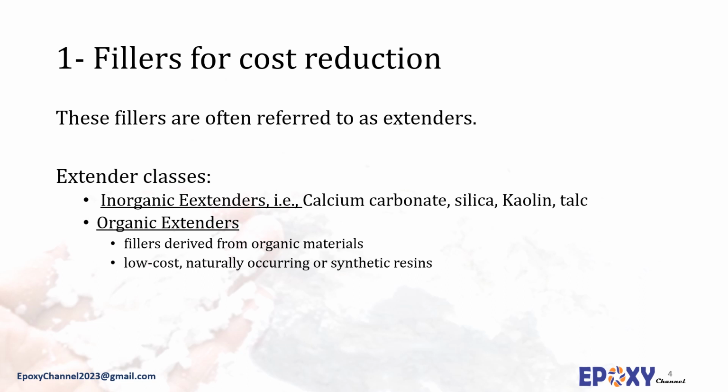Coal tar pitch is the most widely used resinous extender for epoxy resins. It is primarily used in surface coating formulations in the marine, pipe, tank, and general industrial maintenance areas. High boiling point petroleum-derived bitumens are also used as low-cost extenders in epoxy formulations. However, an alkyl phenol must be present as the compatibilizer between the resins and the extender. Further, resins can also be used with epoxies to reduce costs and obtain increased resistance to acids.